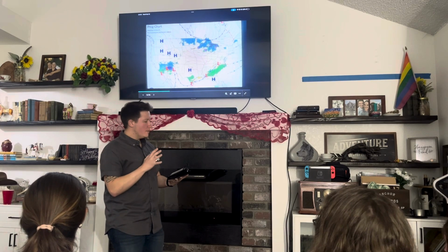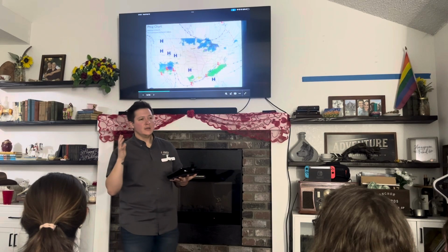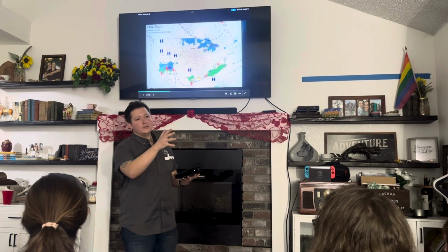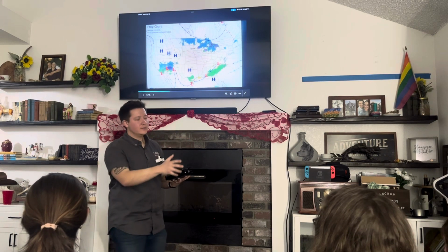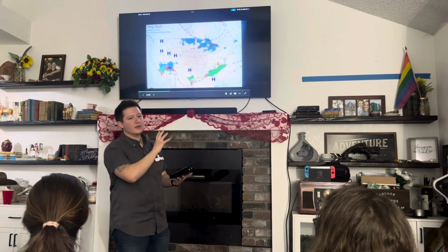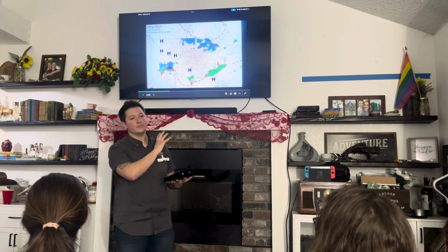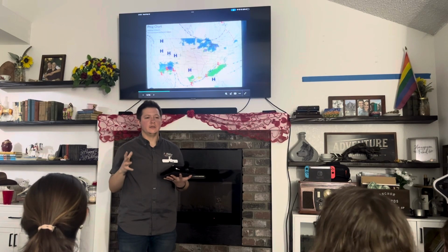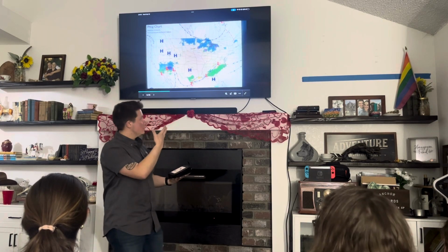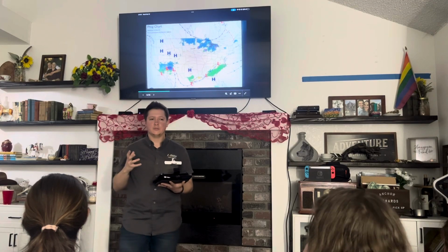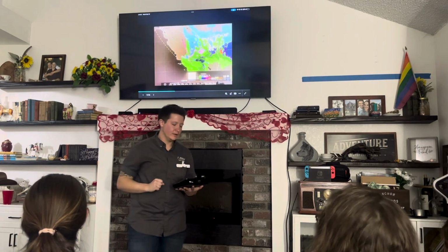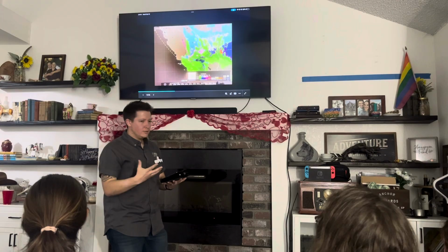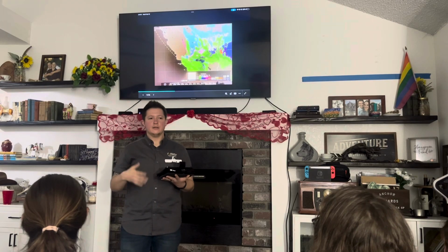And if you have a general representation that there's going to be wind generating from the west blowing to the east, we know that the air mass that this source region is coming from is the ocean. So we already can anticipate there's going to be a lot of moisture in this air mass, right? And thus you can see these different colors down here, which is depicting the precipitation that we're going to encounter. So if we overlay this over our route of flight, you can see that it's right in our way.